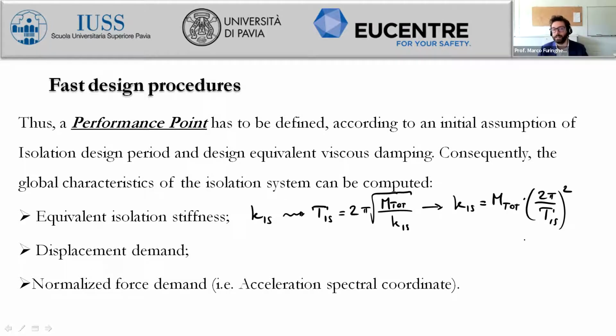We have seen that the standard code for testing anti-seismic devices actually lists the flat sliders as seismic isolators, but we have already discussed why we don't really consider flat sliders as seismic isolators, simply because they don't have any kind of recentering capability, because they are just represented by a purely frictional response.